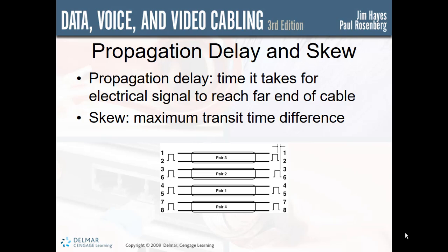The design of the cable has a different twist rate on each pair of wires, and a more tightly twisted pair will have slightly longer wires for a given cable length. Thus, a signal will take different times to reach each end. NVP can also vary with wire insulation, also causing differences in transit times. Some cables have been built with different or cheaper insulation on the pairs, not normally used with Ethernet or token ring, and the variation in transit times may be more than tolerable.